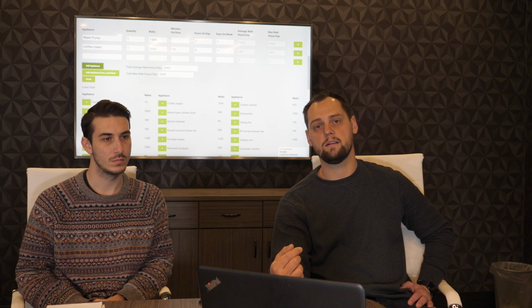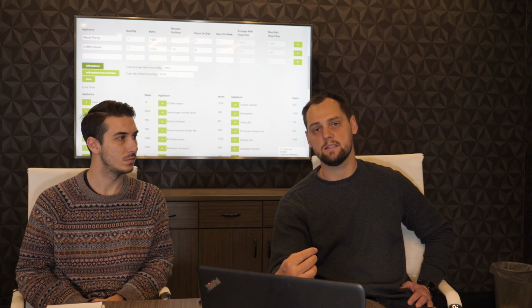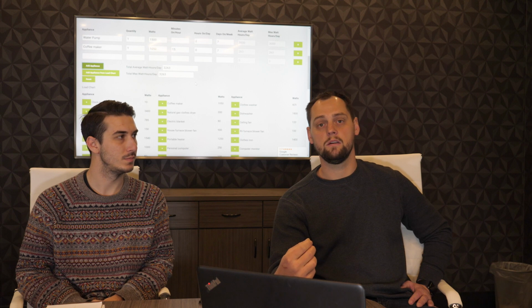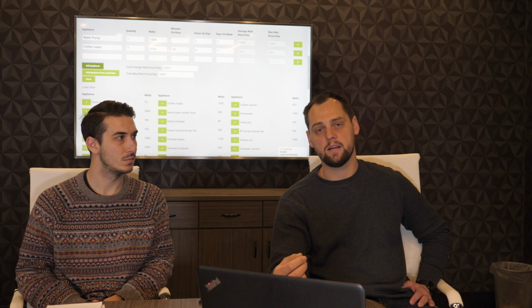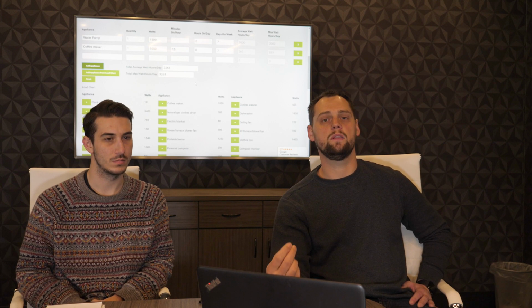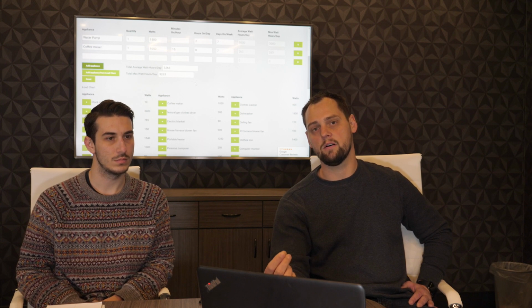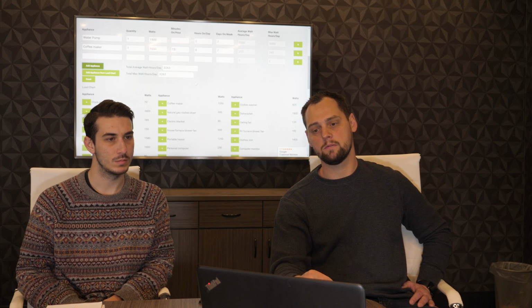So looking back at the appliance and seeing how it's rated, if it's an Energy Star rated appliance, go to Energy Star's website and look up the appliance, and it'll actually tell you what they expect in kilowatt hours a year from that device, and you can figure out specifically what daily consumption that product is going to use.